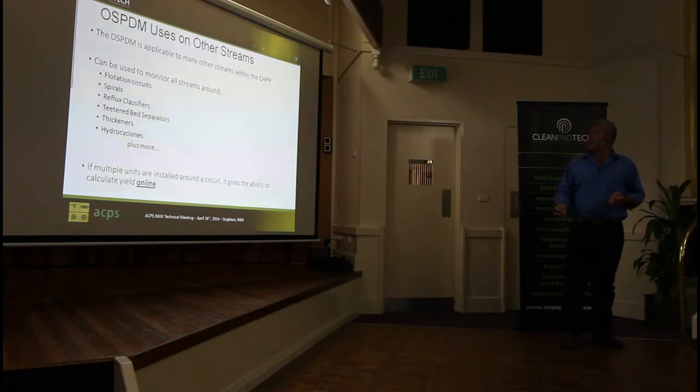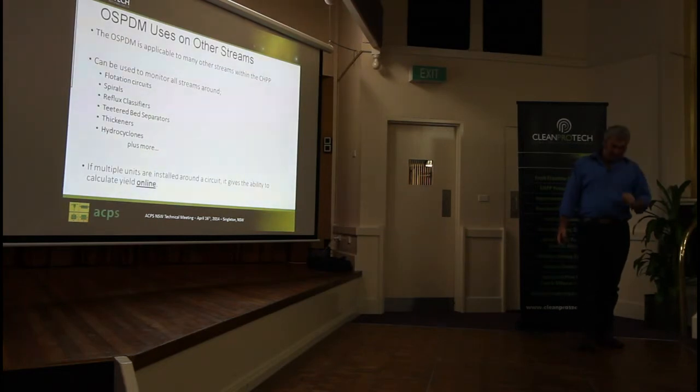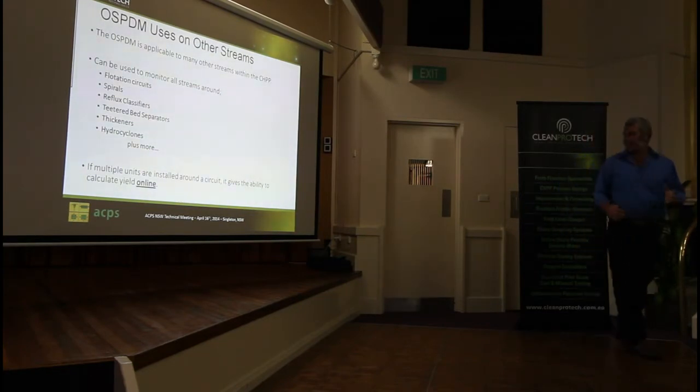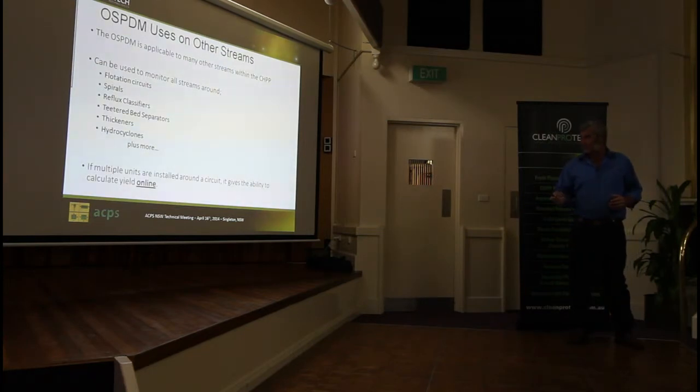That's particularly so now. We have put this on other streams. Bloomfield's is on the flotation tailings, but there's absolutely no reason it can't go on the others. It takes 10mm particles through it, we'll pass them easily. We could potentially go larger, but 10 is fine for the moment, I think, on all those systems.